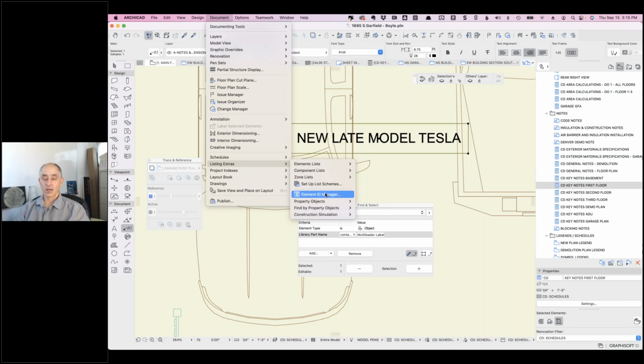You can audit it by creating a schedule similar to what we were doing earlier that reports on everything, and then you can make sure, you can have little preview images of the elements, to say, oh, do I have a cabinet designated as a plumbing fixture? Oh, that's not right. So you can have a report that tells you whether your notes correspond in the way that you would expect. So that would be another management thing, because obviously that's one of the things we all want to avoid, is putting a note that's the wrong number for an element. Yeah, that audit would be a great tool to back it up.